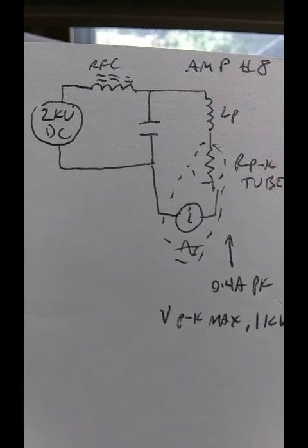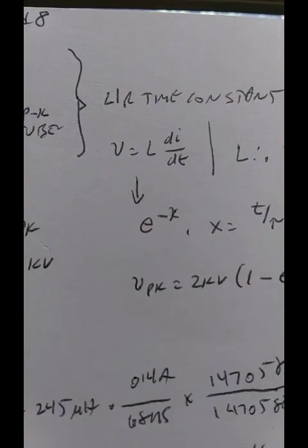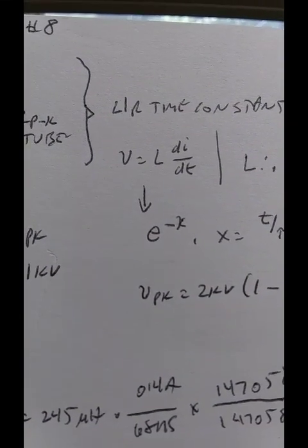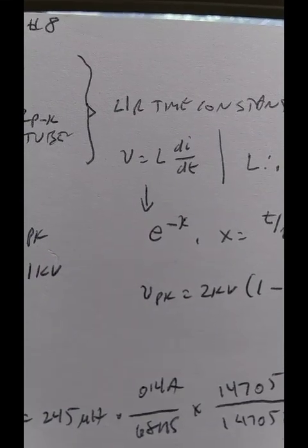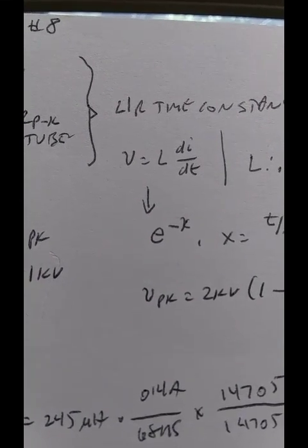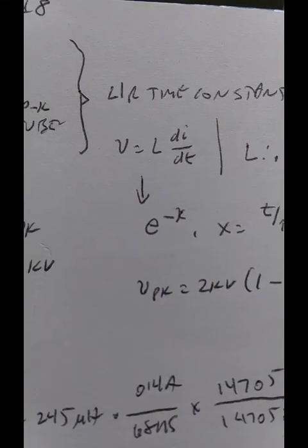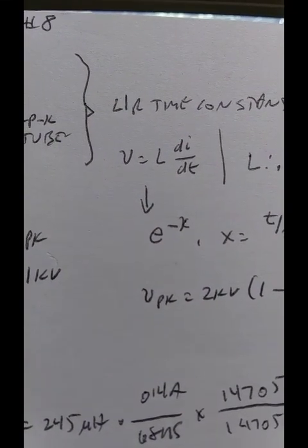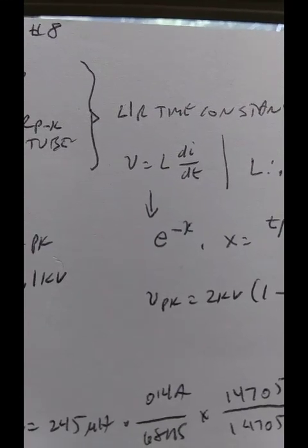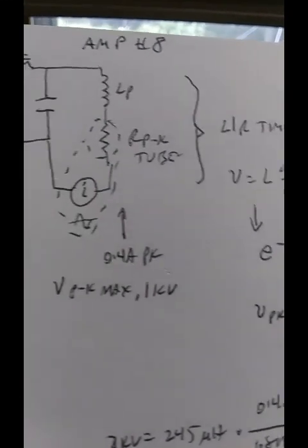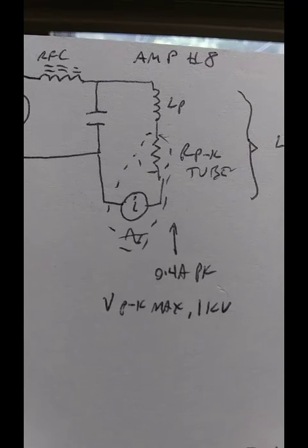And this is a problem in switch mode power supplies. If we go back to the differential equation and set di/dt to infinity, infinity times anything is infinity, so at an infinite current rate, the voltage becomes infinite. Does that happen in the circuit? Yes, it does. At the initial time the current very first starts to flow, the charge in the inductor is 0.